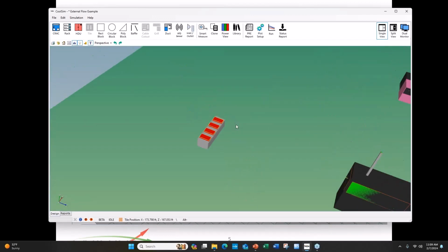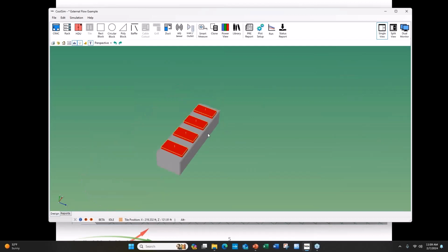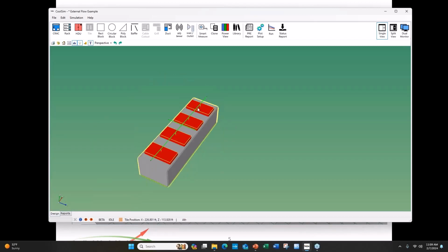Now, there's a couple ways you can do this. If there's a lot of them, and the data center is really quite complicated with a lot of equipment, you can represent the array as a singular structure across, one HDU instead of two. So I could take the array of 8 that I just showed you and turn it into an array of 4 and get an equivalent answer. Now here, again, this would be equivalent to 2 of the earlier fan structures that I showed you, and you would therefore take the total mass flow rate and the total heat load and so forth and do it this way.